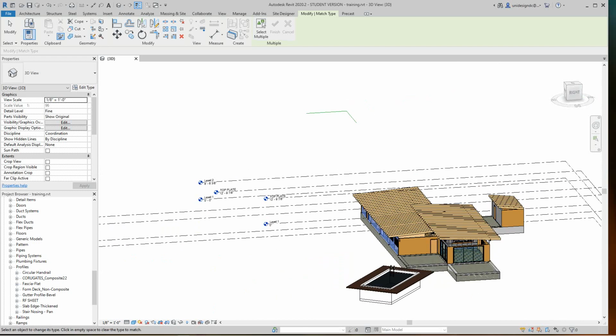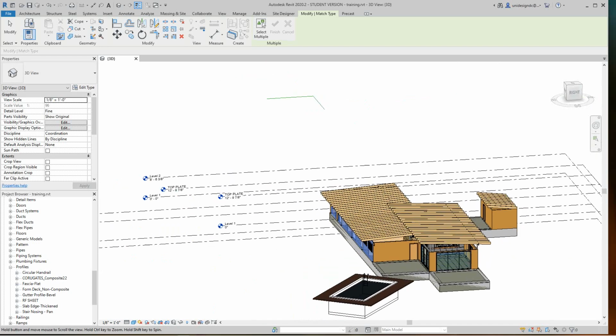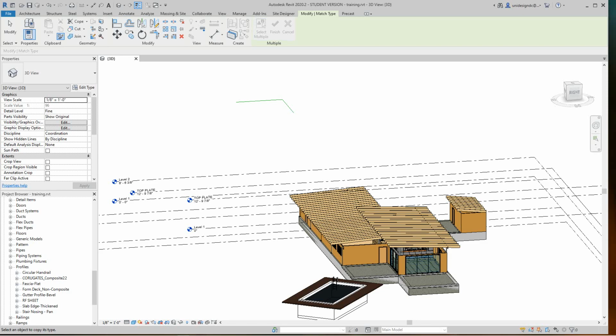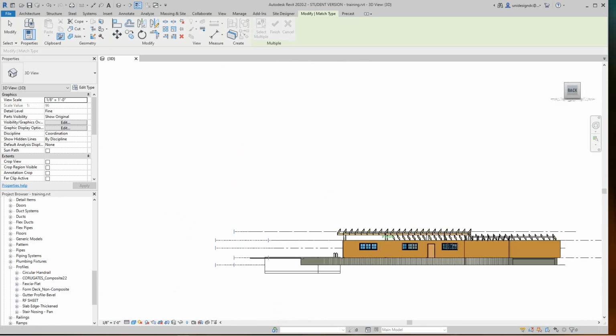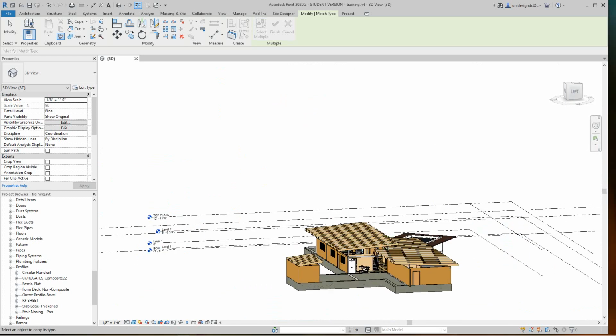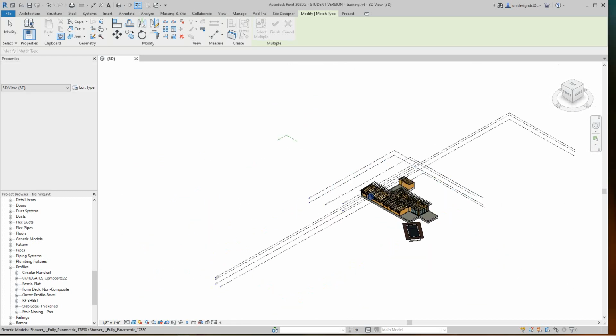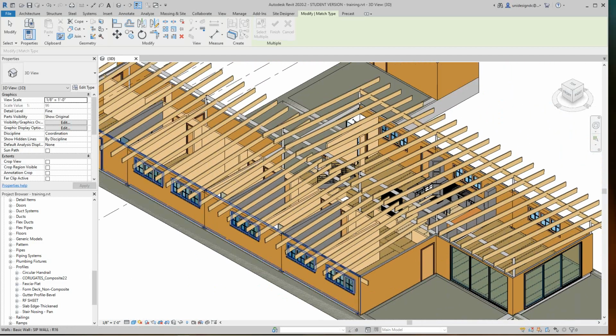Structural in place panels. Now we can split these as well because they come in sheets of 4 inches, but we'll do that another time. It's very simple. You just go on a plan view and do the split command to get the walls to finish the split. So now we have our walls.